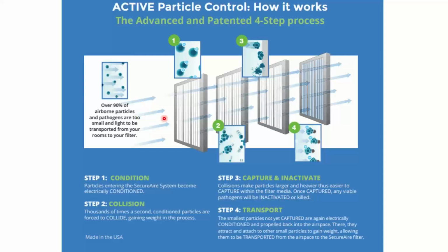Just like those electrostatic filters, we were charging particles one way, let's say negative, and then we had plates positive where they would collect. We're going to charge particles. But this time, we're not going to charge them and then have a plate to collect them. We're going to charge some of them one thing, say positive, and charge some of them a different thing, negative, and then they'll collide into each other. So I'm not charging plates to collect them. I'm charging things, and they're colliding and sticking together. A bunch of positive negatives clumped together, and guess what?